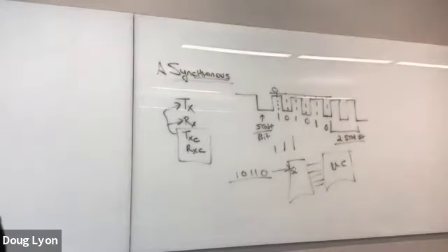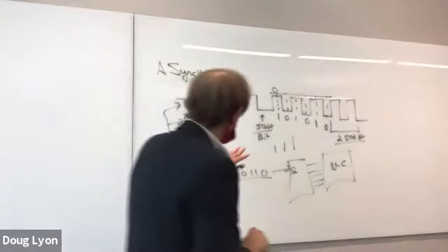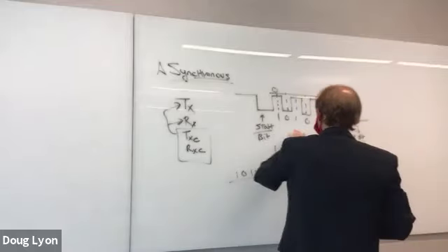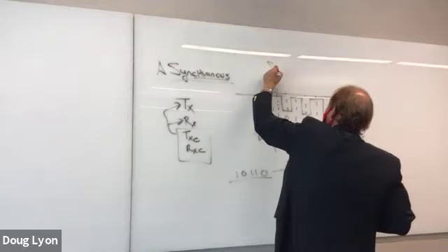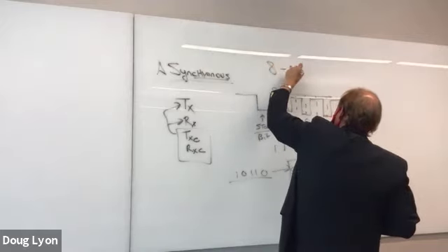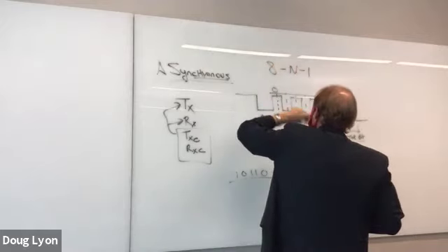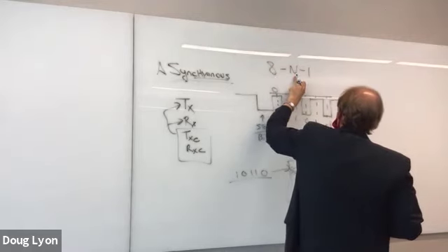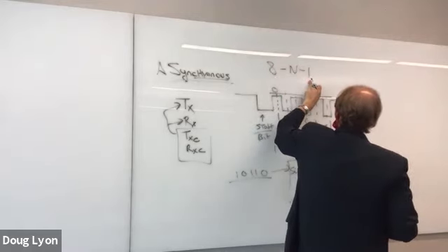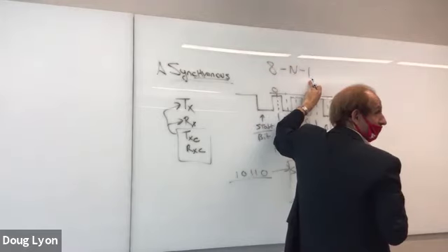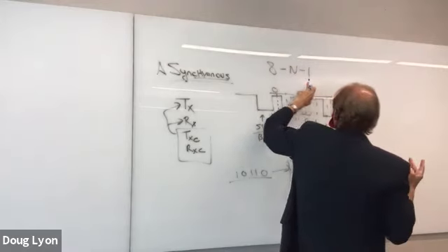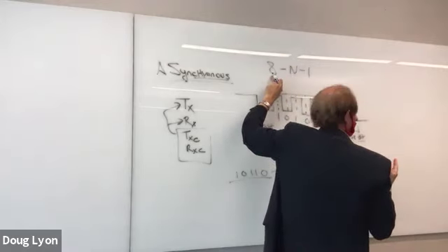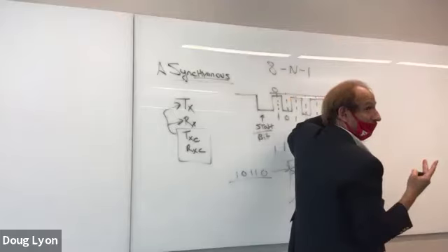So I've got framing bits, start bits and stop bits. I've got data bits, and oftentimes I'll do something like this. I want a serial port with 8, none, 1. 8 data bits, no parity, perhaps 1 stop bit and 1 start bit. If that's the case, then I've got 2 bits that are just being used to frame and synchronize the receiver. And 8 bits worth of, I will call it payload.